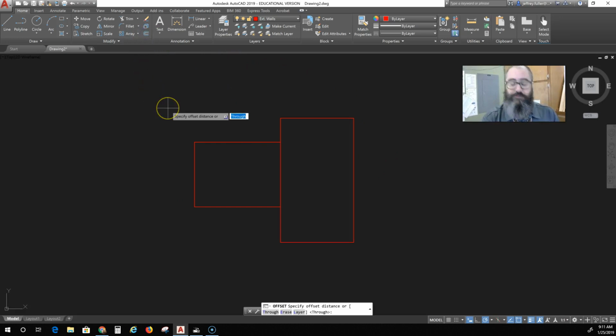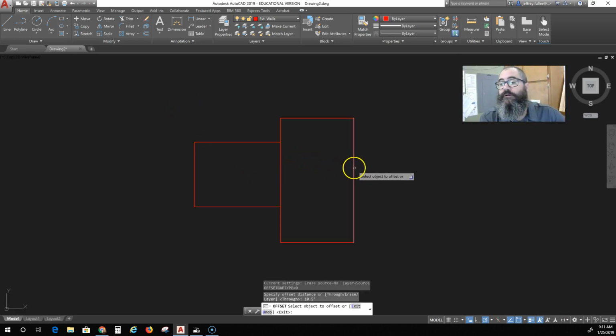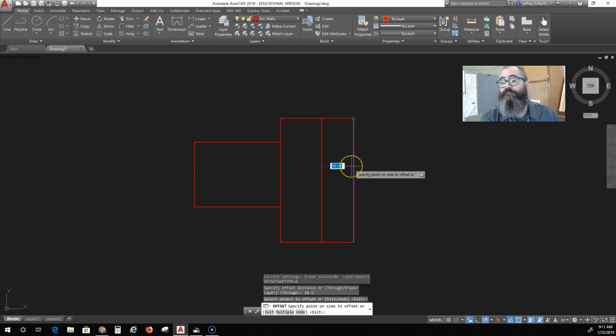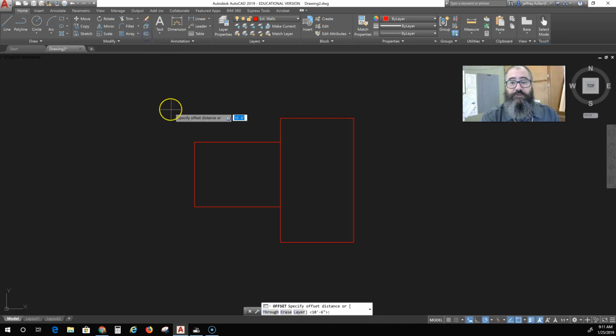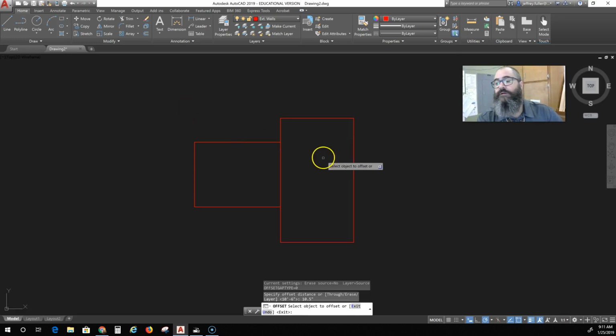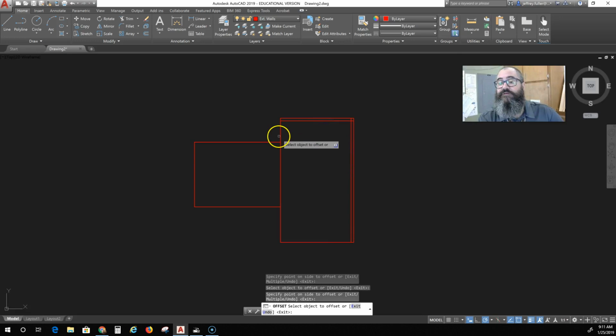I'm going to click on my offset tool and do 10.5 feet. Oops, 10.5, wait, no, 10.5 inches, I'm sorry. Sometimes I just leave it there. But anyway, 10.5 inches, that's more like it. And I'm just offsetting all of these lines to make my exterior wall thicknesses.